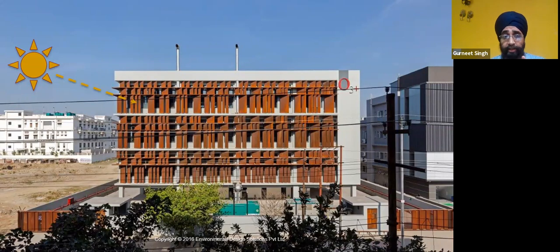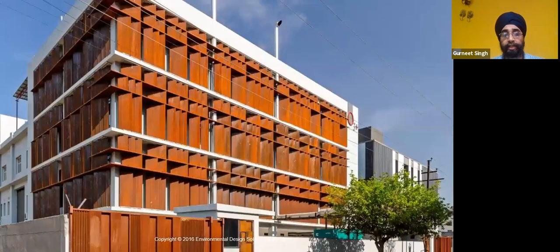We were able to cut the sun, and along with the visual comfort level, we were also able to achieve the thermal comfort level. Since this is a southwest facade, it is exposed to sun after 3 p.m., which is a low angle sun. That's why you see this as a vertical fin at an angle. This is another view of the angle.